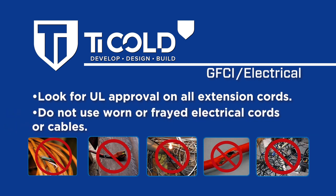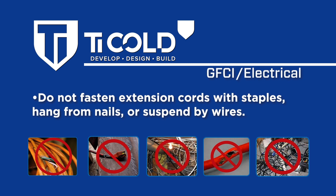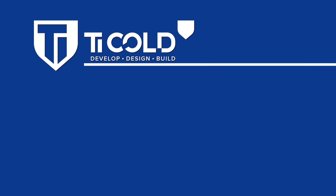Do not use worn or frayed electrical cords or cables. Do not fasten extension cords with staples, hang from nails, or suspend by wires. Locate extension cords out of traffic paths and secure in place with duct tape.